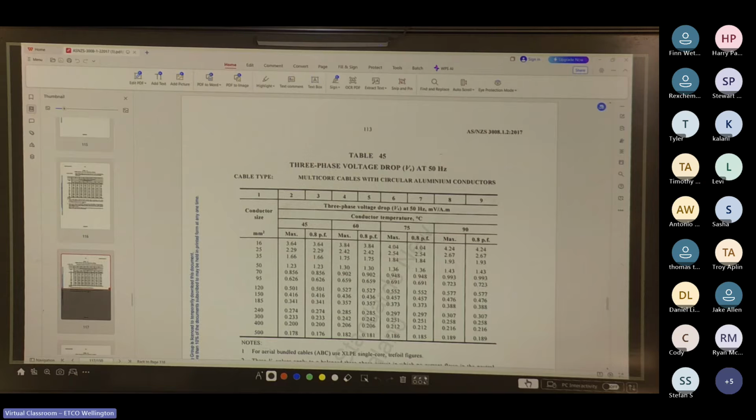Current carrying capacities are based heavily on the factors we've talked about just now. There's a variance to ambient temperature. We need to uprate or downrate the cables using the different tables. Once we have the right table, we scale it down within the table to the right columns. Firstly, we pick the right environmental condition. Then, is it copper or is it aluminium? If it's copper, is it solid, stranded, or flexible?